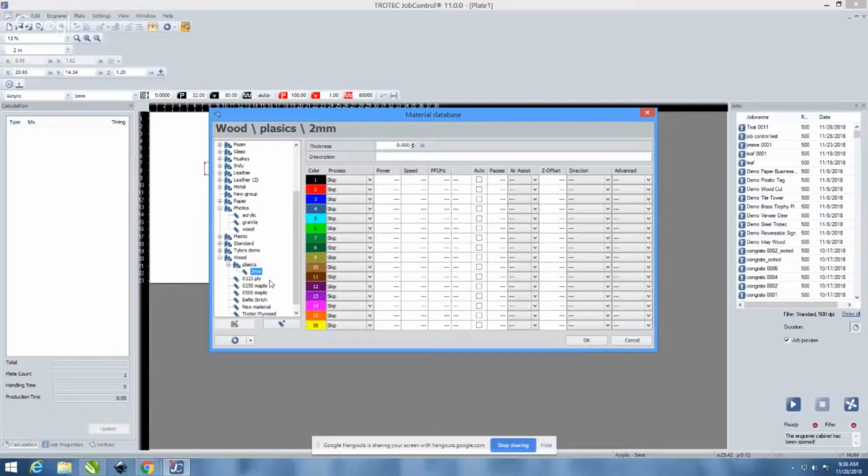that I will post in the description afterwards, that you can use for testing the perfect engraving that you want. And then you can save those settings, not just for materials, but even the settings that you want. For example, if you want to engrave a clear acrylic, you'd go out of focus. You can save that setting. If you want to engrave white on acrylic, it'll be in focus, so you can save that as a separate setting. So this is why it's such an amazing tool to use within JobControl.